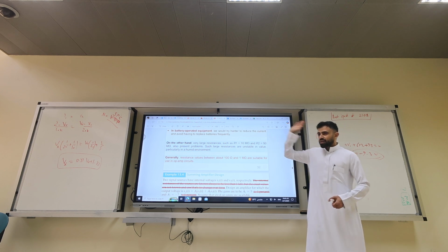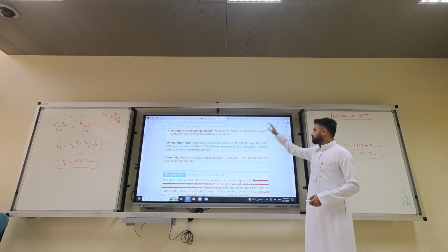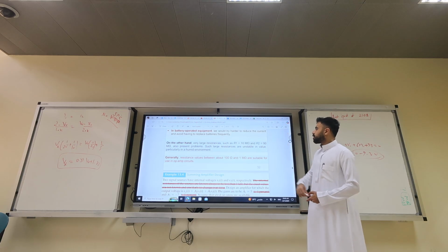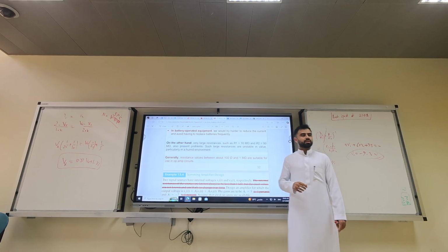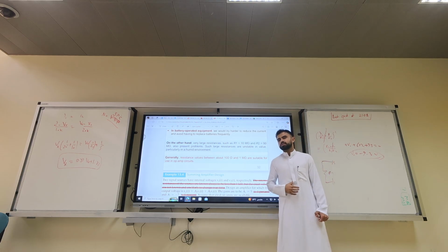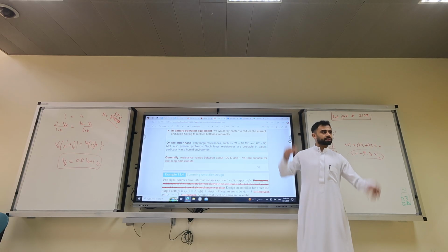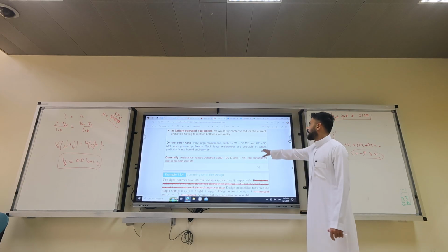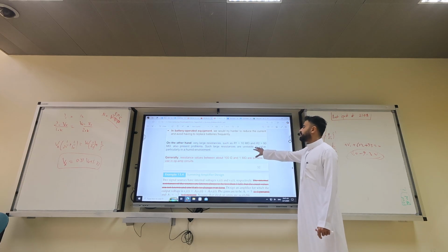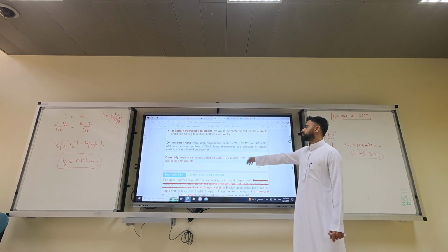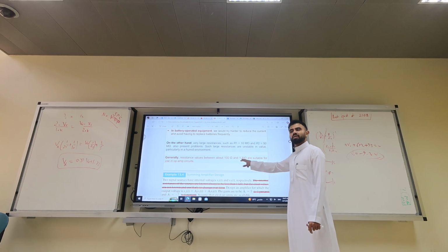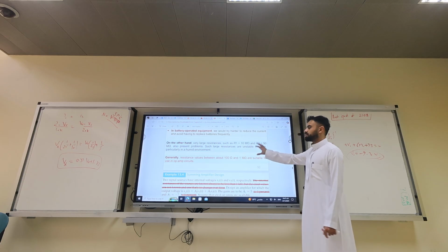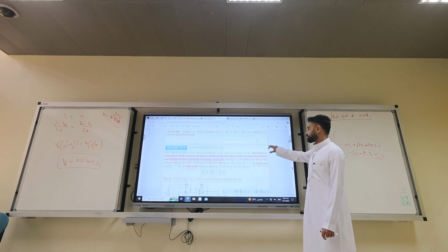On the other extreme, if we have 10 mega ohm or 90 mega ohm, those large resistances will not draw any current. It will be virtually like an open circuit. And they will cause issues with stability, they say, in humid environments. So generally, what should you pick? Between 100 ohm to 1000 kilo ohm or 1 mega are good design values, okay?